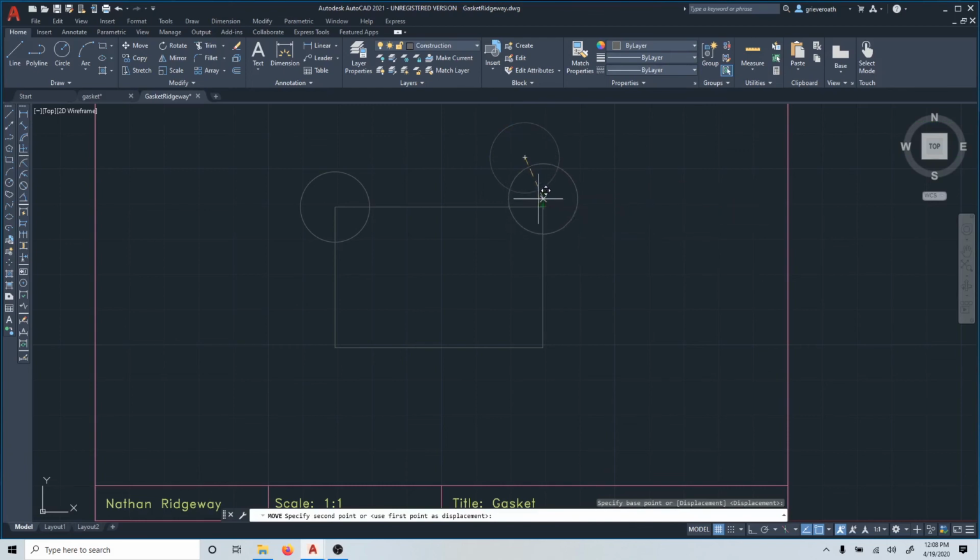If you're having trouble moving it, if it's stuck on these axes like this, you have ortho mode on. So you can press F8 to turn that off. Or you can click on this L shape right down here. I'm going to snap it to that corner. Another way to do it is just use the radius again. And we just click 0.5.